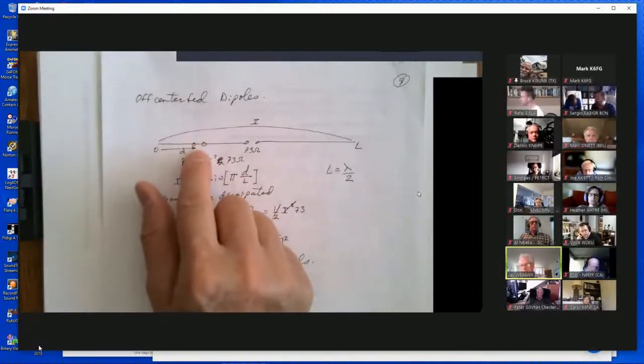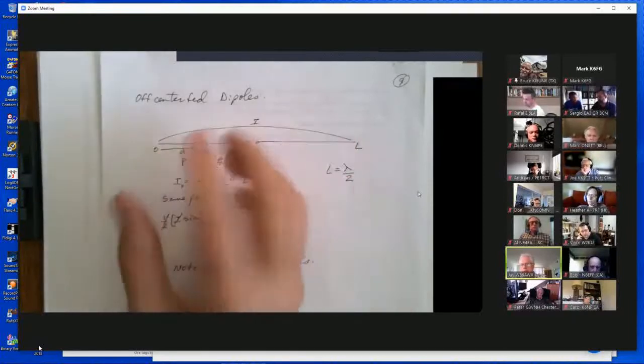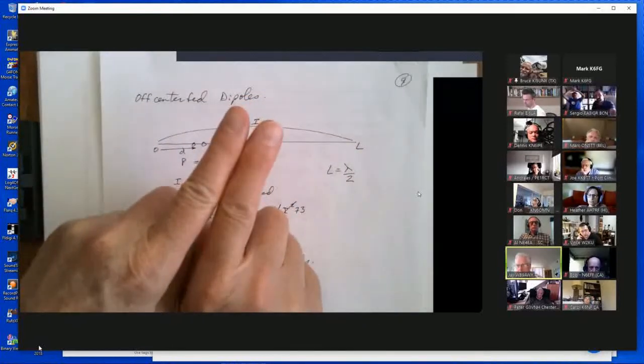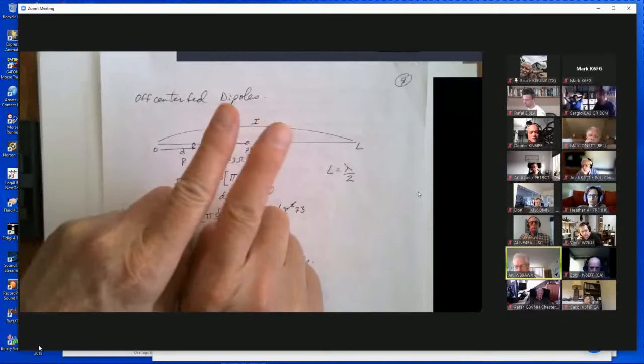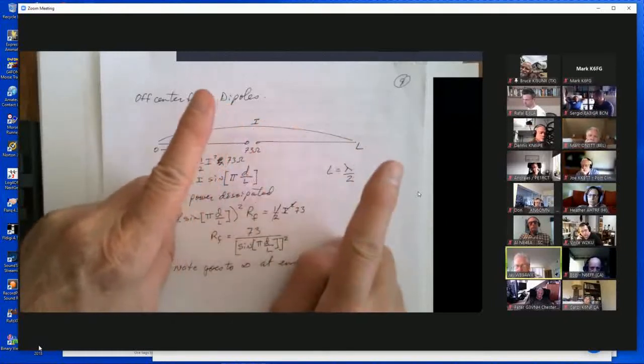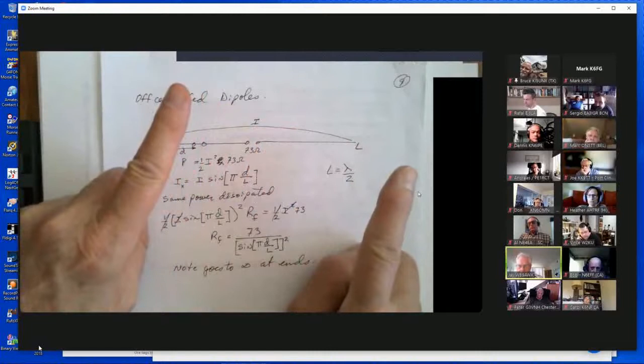The question is about ladder line pickup. Ladder line, unlike coax, if you have coax that's laid, you can run two pieces of coax almost next to each other and get very little crosstalk. Ladder line, you can't do that. Okay, the fields cancel when they are a significant distance apart, and that's what keeps them from talking to each other. So you want to keep ladder line away from other things.